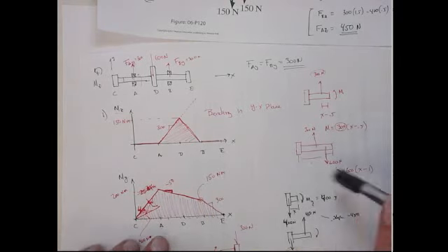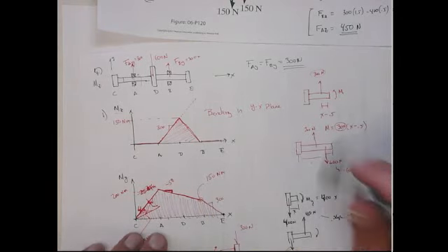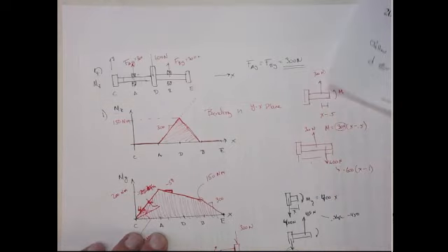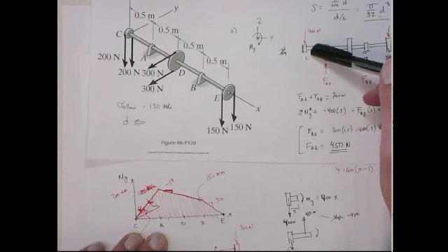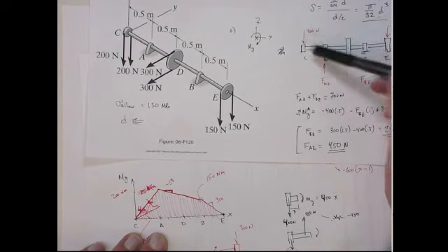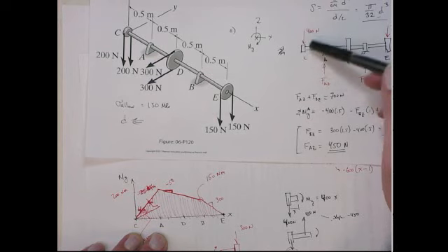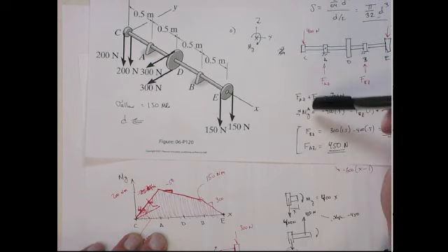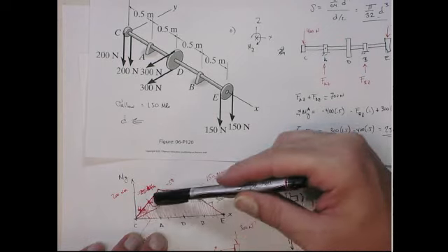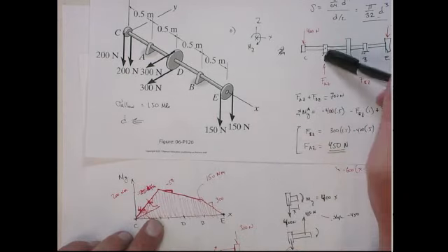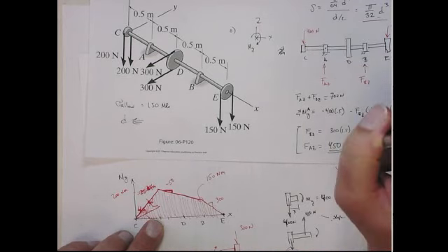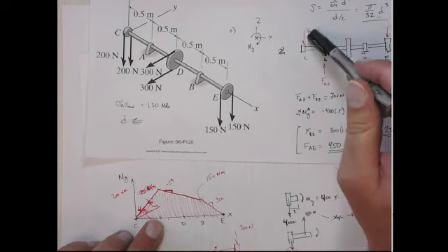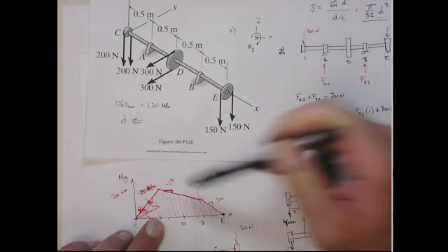All right. Likewise, when we go from C to A, first we have the 400. This one turns out to give us a positive bending moment because the positive bending moment sense flips in that plane. So it slopes up at 400 until it gets to point A. And at point A, we have the difference of these two. So we have positive 400 and a minus 450. So the net slope is minus 50.